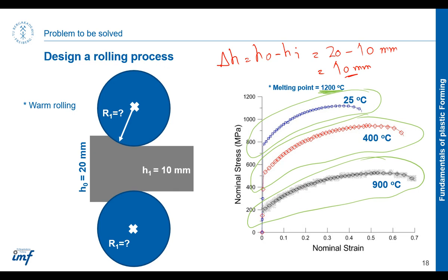Okay, super. And from here, for example, if we have 0.69, which is almost here, strain in the material, the flow stress required to achieve this is somewhere here, and that is something which we need to plug in that equation and get our output for total force which will be required to do this process.